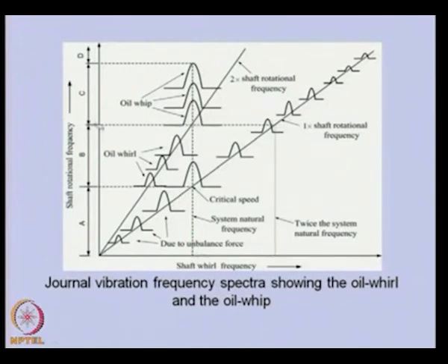So, the rotor is rotating now at twice the natural frequency, and at this particular speed we do not expect much vibration in the 1x component, but here we have a very large amplitude of vibration. Let me define these amplitudes. These are called oil whirl. These amplitudes are relatively smaller. Oil whirl phenomena are not so dangerous as compared to this particular condition, in which we are rotating the rotor at twice the critical speed, and because of that, at this position the whirling frequency is equal to the natural frequency of the system.